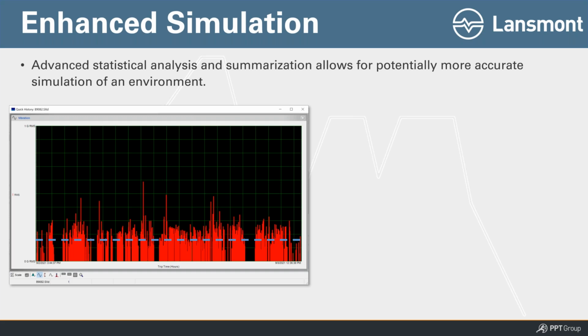And so if I exported that, I could run a test that had an average GRMS of 0.157, and you might say that simulates the ride. And what I would say to that is that, well, it might, but the reality is, this is the average. So some of the vibration that was experienced was less than the average, and some of it was greater than the average. I don't really care so much about if it was less than that, but I am, as a shipper of products, concerned with the big stuff.